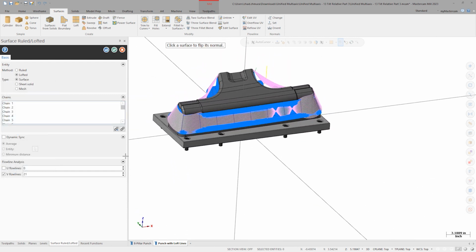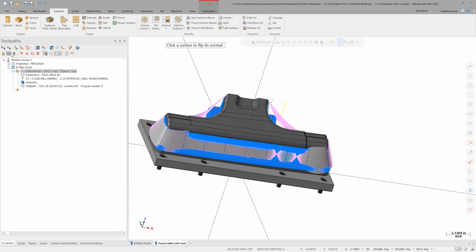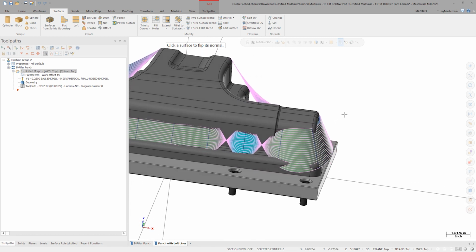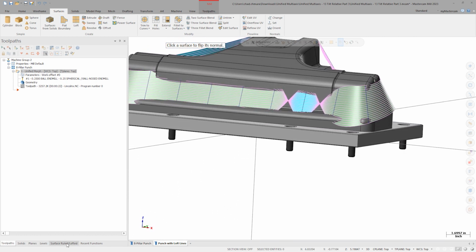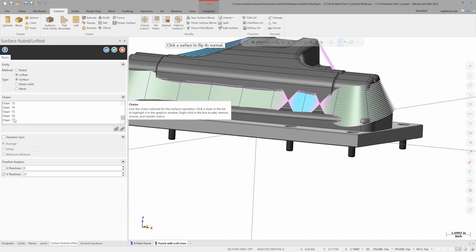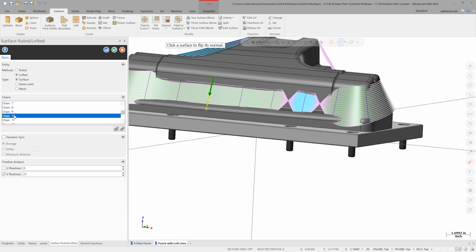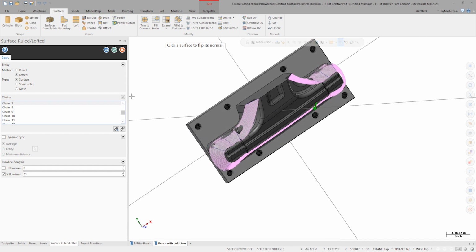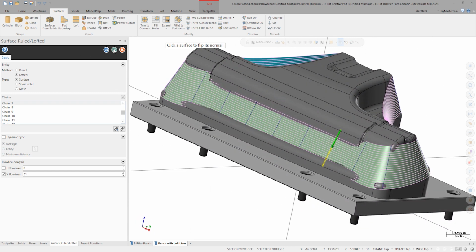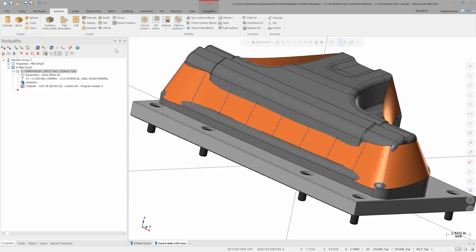Once the lines are selected, we see the new lofted surface tools available in Mastercam 2023. If we selected any of the lines in the wrong direction or out of order, or if we missed any lines, we now have the opportunity to correct our selection before the surface is made. We even see a live preview of the surface as we make changes. If we see the backside of the surface, shown in green, facing outward from the part, click on the surface once to reverse the normal direction.